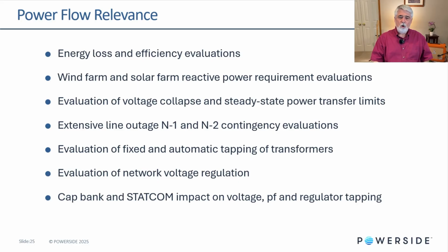Wind farm and solar farm reactive power requirements. These evaluations are being done right now, all the time. Wind farms are going in, solar farms are going in, and they have to meet reactive power requirements because they are now generating sources and are replacing conventional generation. They have to be able to hold and support voltage and supply VARs, similar to conventional generation.